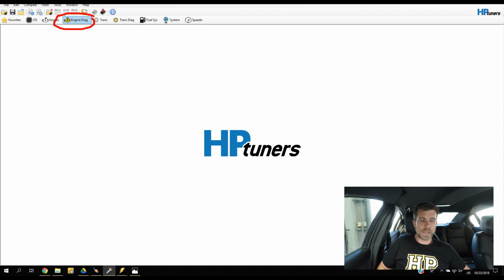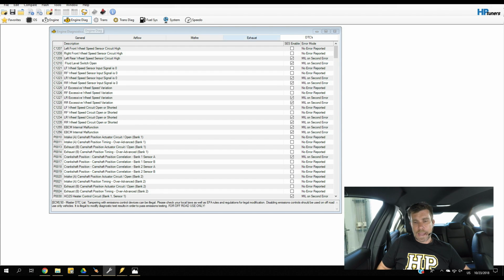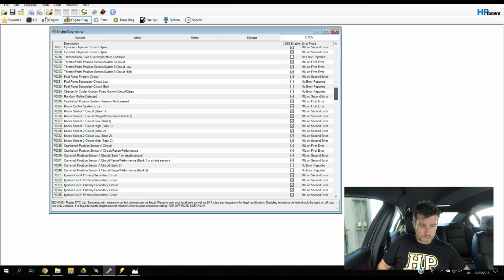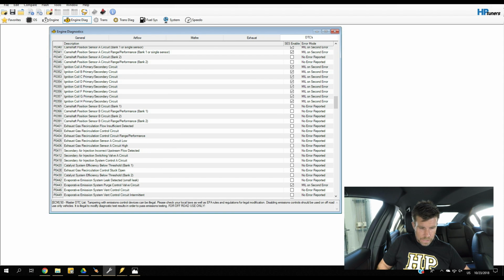So we can come across here to our engine diagnostics tab, and we're over on the right hand side at the moment on our DTCs. You can see there is a massive list here. What we'll do is come down to the one I was talking about. So let me see here. Alright, so P0420, my memory was pretty good. We've got catalyst system efficiency below threshold for bank 1. You can see that I've already taken some action here. This car actually has a high flow set of catalytic converters, but for a couple of other reasons currently got these disabled. So what we can see is we've got the ability here under our error mode on the right hand side.